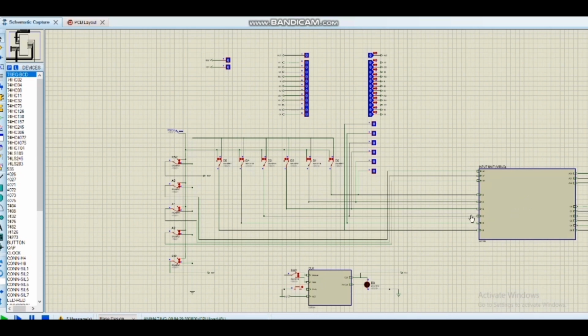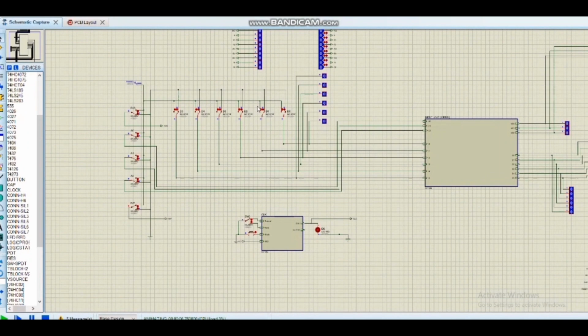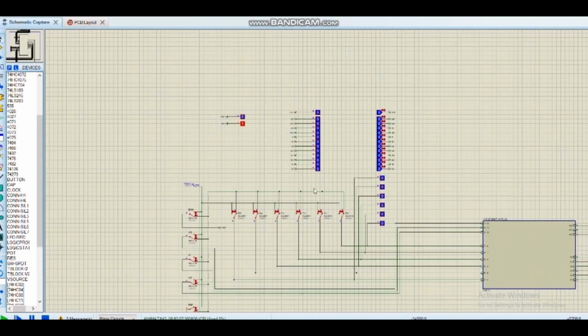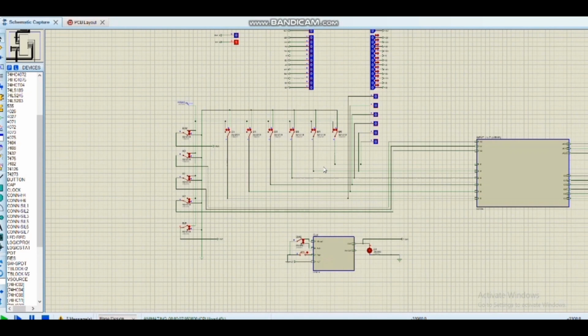So what instructions we have already said should have been done by the instruction register automatically, we can give the same input manually. So we will now be giving this instruction manually. Let's say we need to insert some values in the RAM location 000, and then store that particular value in our accumulator, and then give some information in our RAM location 001, and we want these values to be stored in our B register.